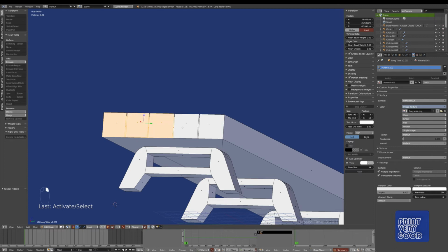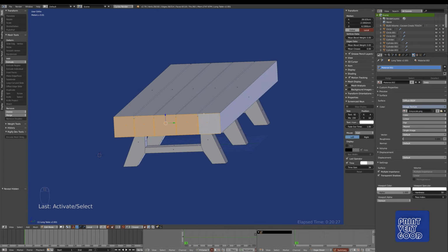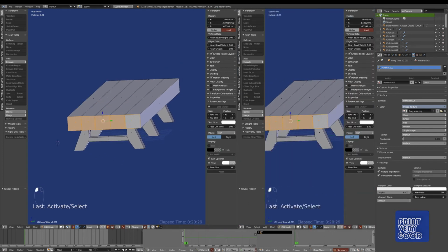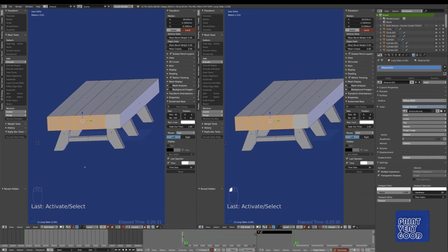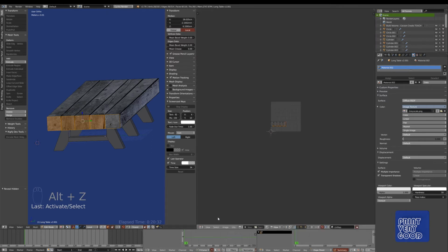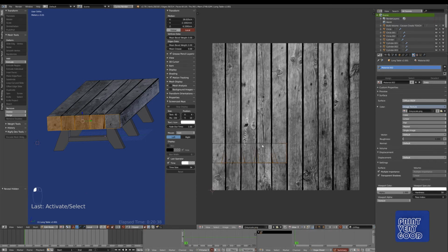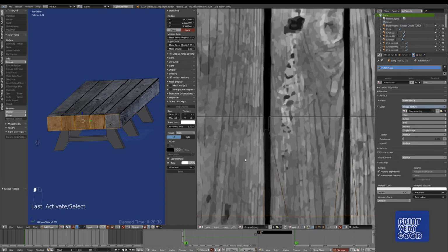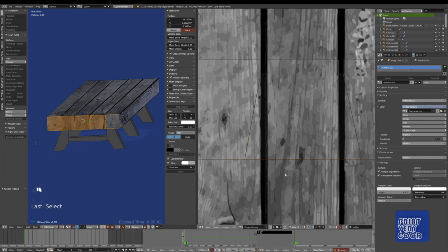And selecting all the faces I want, I can reopen my UV image editor window and load my grayscale image. And we can see here how the UVs are marked up. We can now fix that in the UV image editor window by just dragging the vertices over and lining them up correctly, which will fix our tearing in our mesh, or in our image texture.